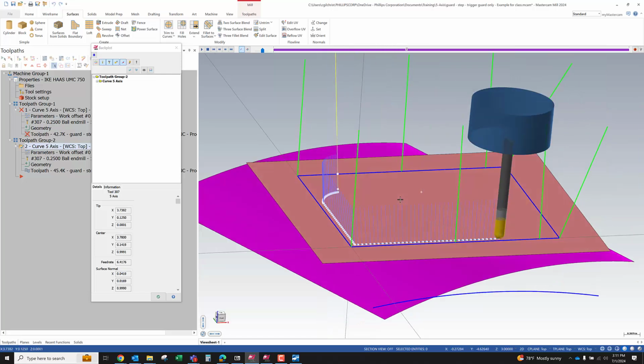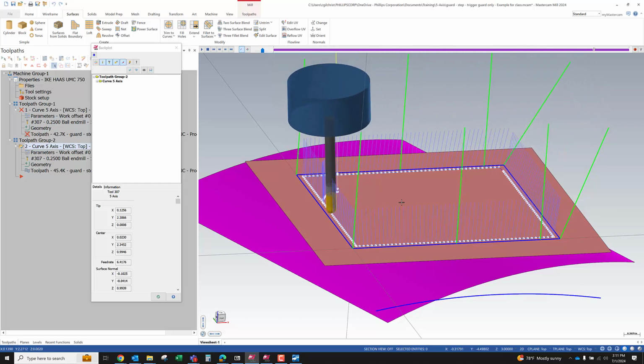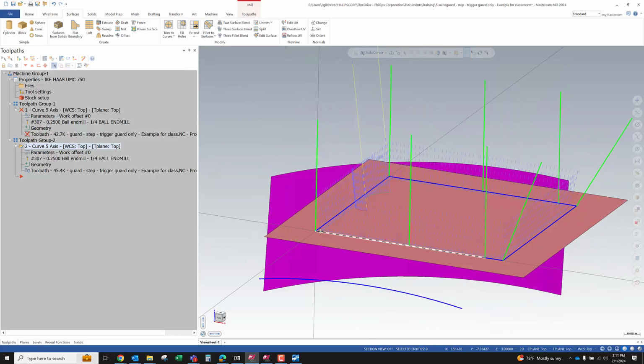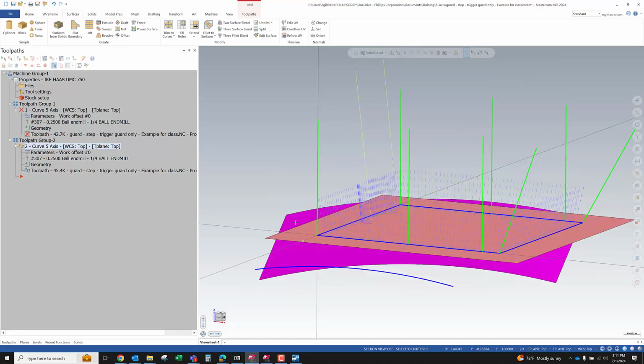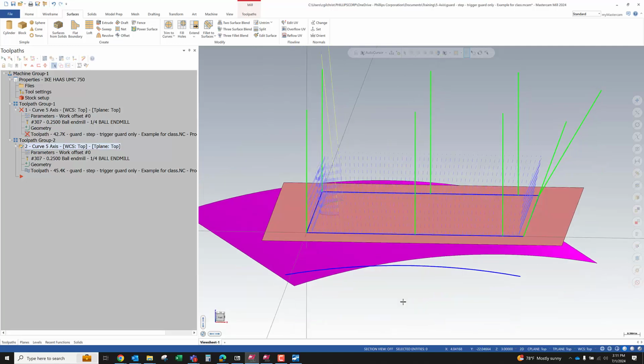So now I'm tilting through multiple directions as I drive this toolpath because I'm driving a surface underneath, and at every position along my chain, I'm projecting down a point and then using the normal direction of the surface at that point to control the orientation of my vector. Now, would I use that rotated surface underneath like I just showed in the example? No. But I'm just pointing out some different methods of tool control.